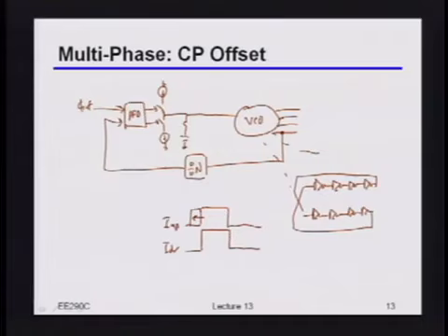Okay? So it turns out the way you can actually do this is quite clever. What you basically do is, if you want to intentionally introduce an offset, you just intentionally skew the up and down currents. Okay? So in this particular example, whatever CDR control bits you had, you would use those to actually program the down current relative to the up current.